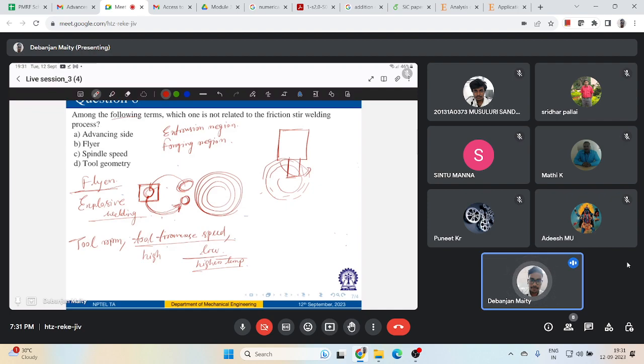There are other specific process parameters regarding friction stir welding. We call it tool tilt angle. You can tilt the tool also. A suitable tilt angle ensures effective holding of material by the shoulder while you are moving the material from the front to back. So you can tilt the tool like this when you are traversing along the workpiece material.